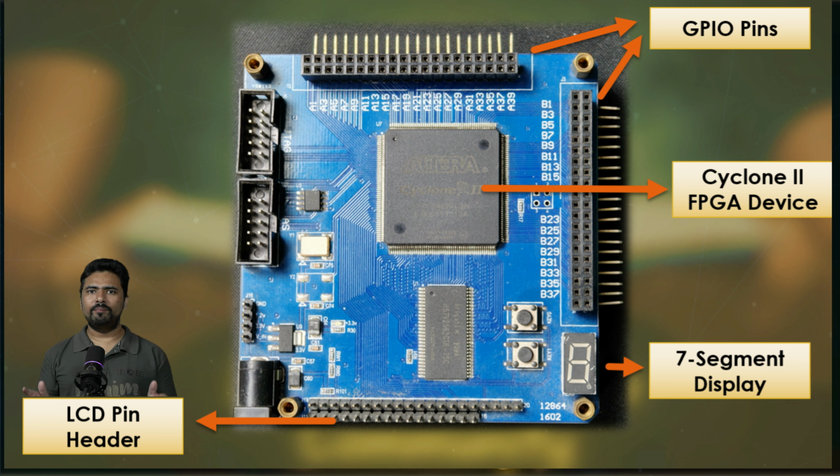Additionally, I will provide a basic introduction to the timing analyzer and how to create basic timing constraints, including generating an SDC file. However, this coverage will be introductory. For verification and simulation, we will be using ModelSim. I will demonstrate how to create and compile ModelSim projects, write module-level and system-level test bench models, and use text files to generate input and output vectors for testing.